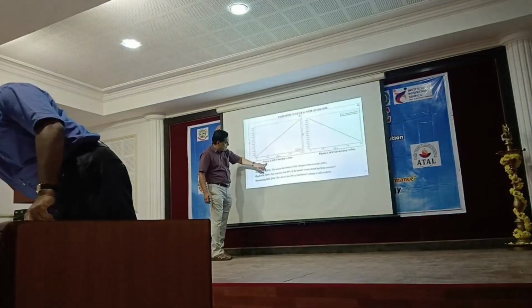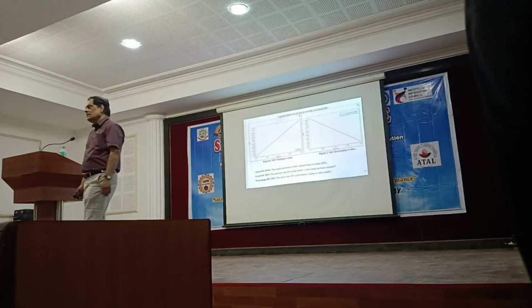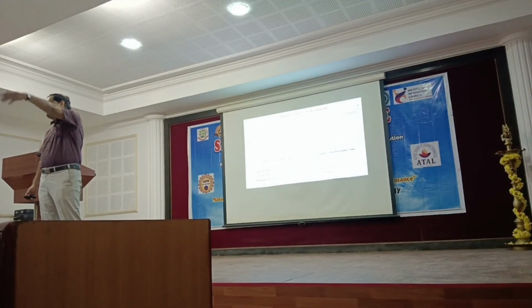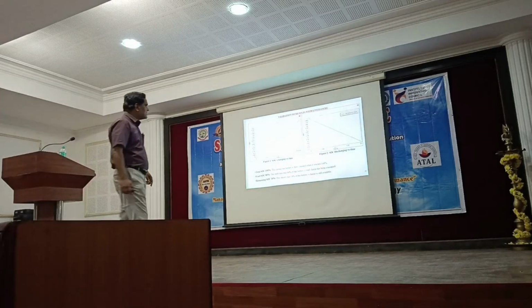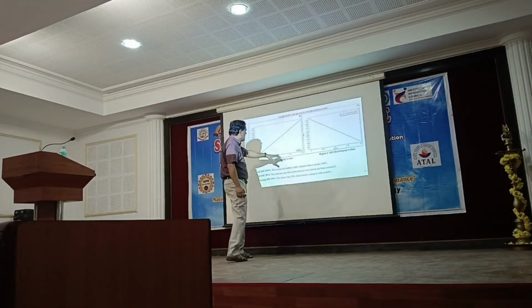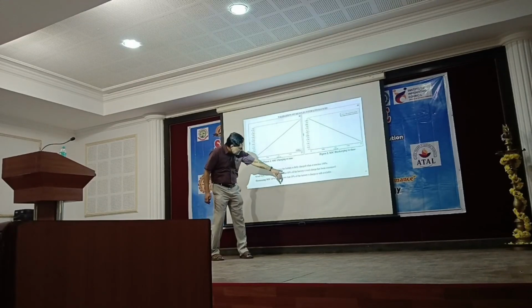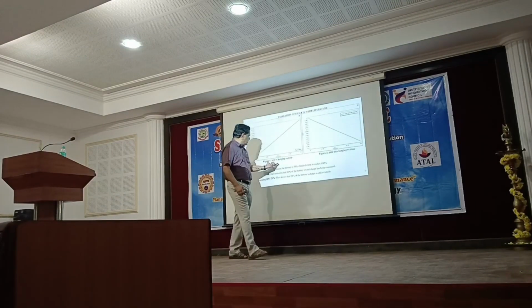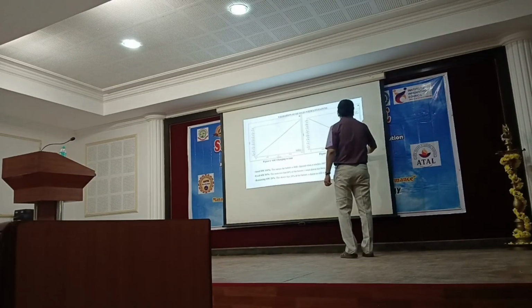SOC versus charging time to achieve 100% SOC. How much time is required for the particular lithium ion cell chemistry to reach 100% SOC? Again, accounting for the C rate of charging, I can estimate how much time it takes to reach 100%. Total SOC 100% means the battery is totally charged. This is the SOC charging time. This is for the SOC discharge time.